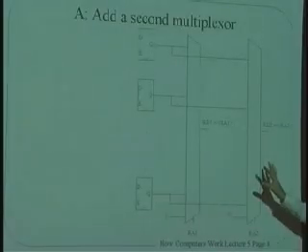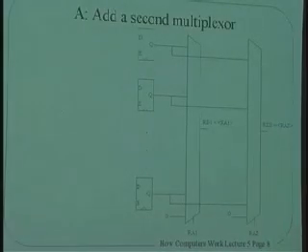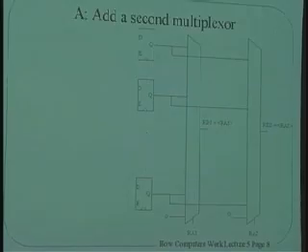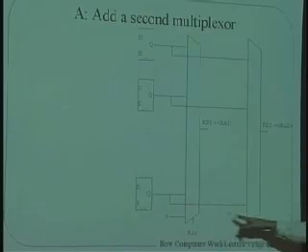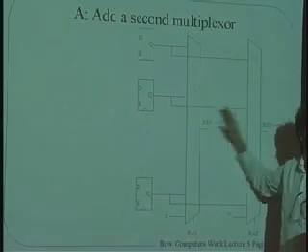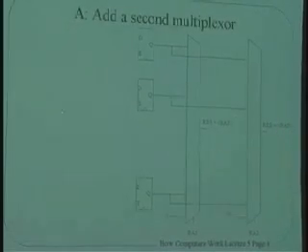Is this clear? Are there any questions about the sort of trick that we're doing here? Yeah? Can you put in any value in each? You absolutely can. There's nothing wrong with saying, I want to add the contents of R0 to the contents of R0 and put the result into, let's say, R1. Okay, it turns out you can also put the result into R0 as well, and we need to talk about what happens when things go around in a loop. But for now, let's not worry about that and just say, sure, there's nothing wrong with putting the same number in here as the same number in there, and you know that both of these selectors will select the same thing, and you'll get the same data out of both of them. Okay, so this is a 2-read port register file.